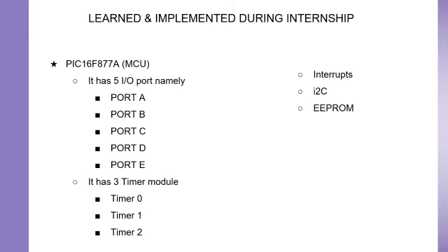What is meant by timer and interrupt? The timer is an important application in embedded systems. It maintains the timing of an operation in sync with the system clock or an external clock. The timer has many applications, such as measuring time and generating delays. They can also be used for generating baud rates. A normal delay function might use a for loop iterating for a few thousand cycles, but these types of delays are not accurate, and fundamentally it is not a good programming practice.